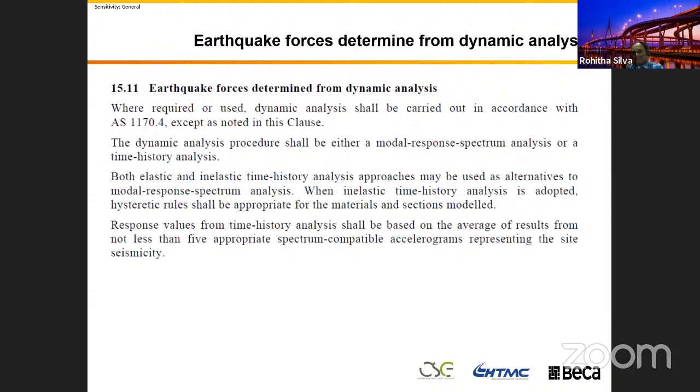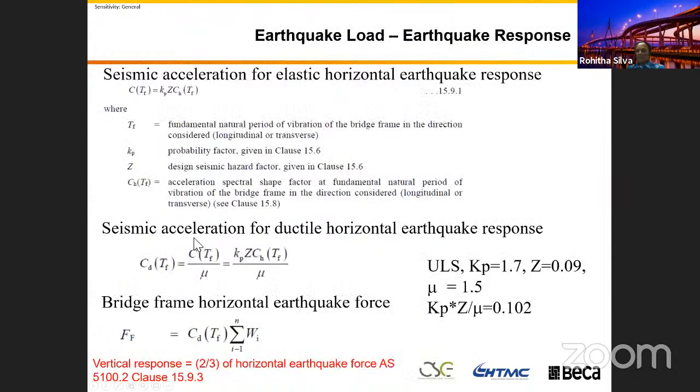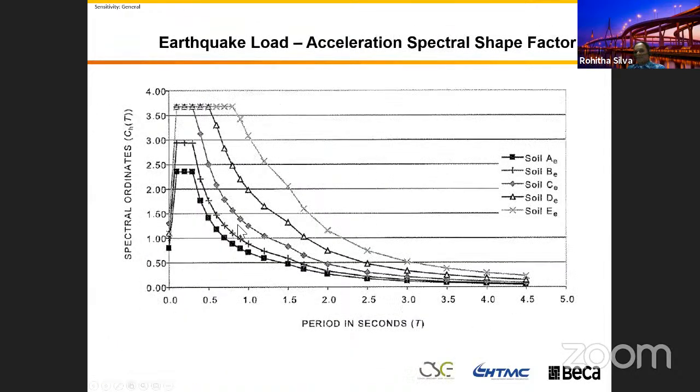If you have computer software capable of analyzing that, you can use it. Otherwise, you can just use an iterative approach. For example, you can play with the average one, because we have a peak value, and you can compare it against the natural period of the structure as well. If your natural period of the structure is, let's say, beyond this 4.5 seconds, then the average value you design with makes sense.